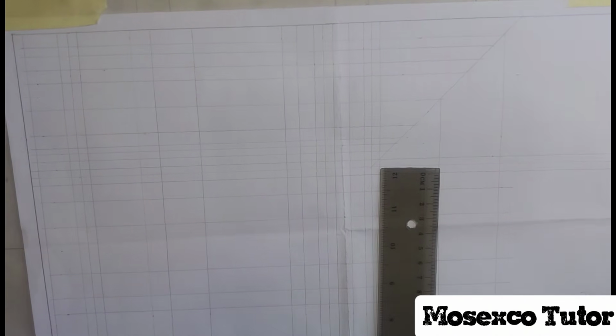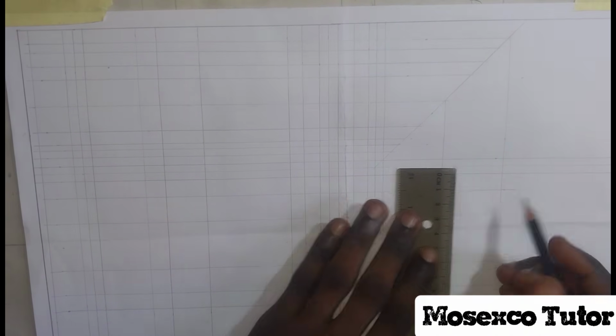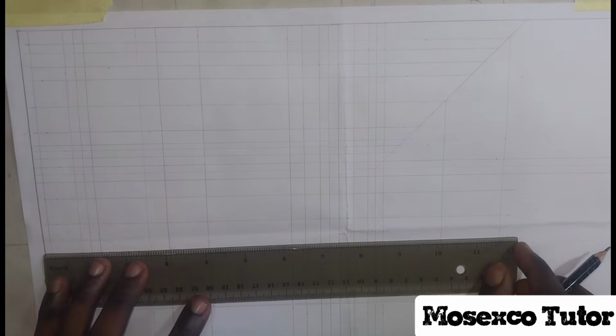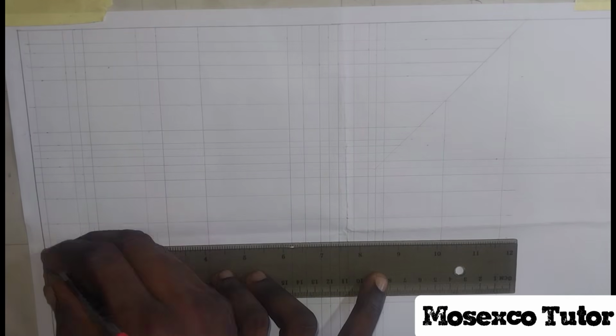Now to get the mid of 8 is 44, so that's 4.4. So from this line, which you can see there, which is the third line of the marginal line, I take 4.4 down. If you take it from down to that point, it will also be 4.4. So I take 4.4 down at the other side also. If you check, it will also be 4.4. I join it together as faint horizontal line. Now, with me getting all these lines, it means I'm good to go with getting the diagram.